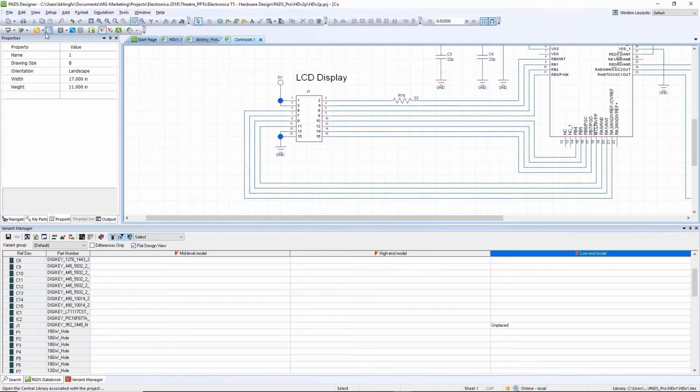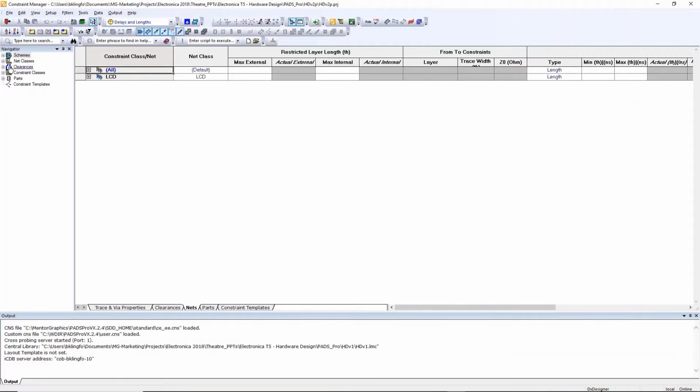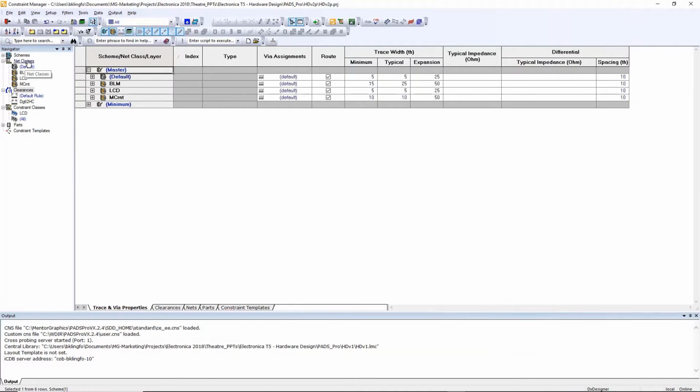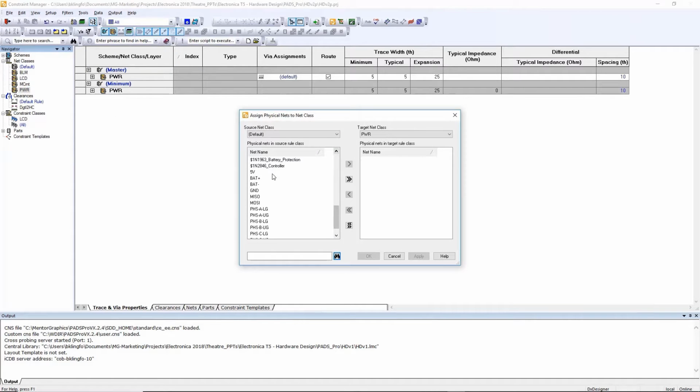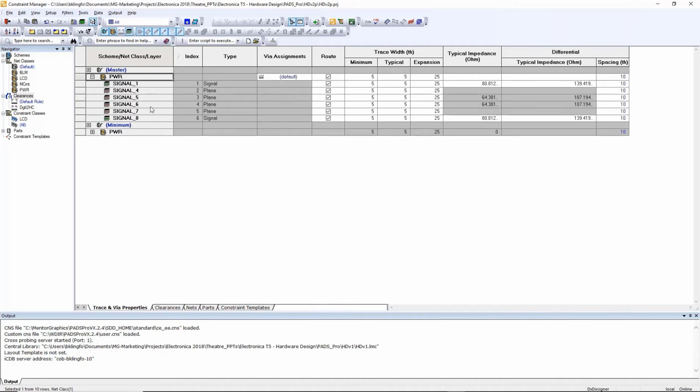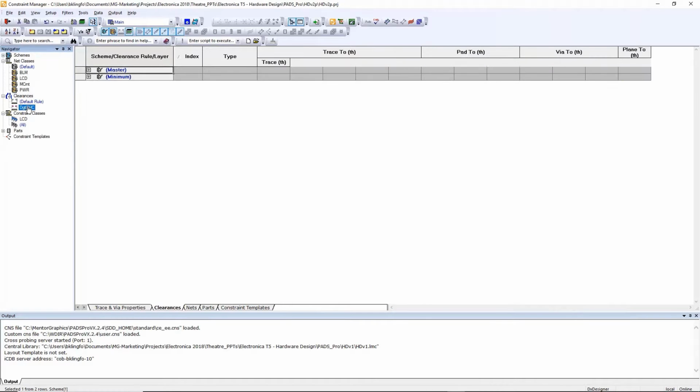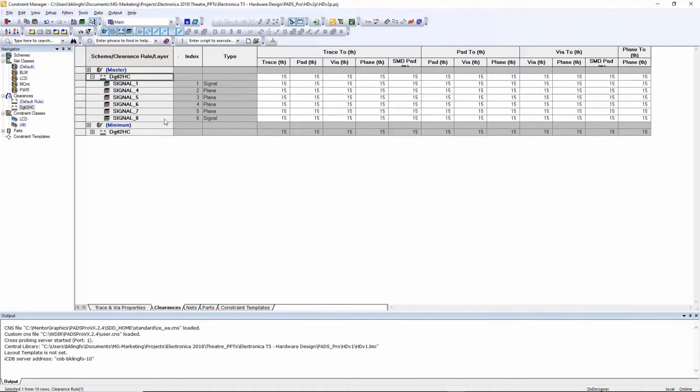Moving on, design rules are mandatory for doing a PCB layout. In many cases, it's much easier if you can enter as many design rules at the schematic level when you're thinking about your electronic circuits, or you've done simulation. So from Designer, we can open up the Constraint Management System, which is the same rule entry system you would use in the PCB layout.